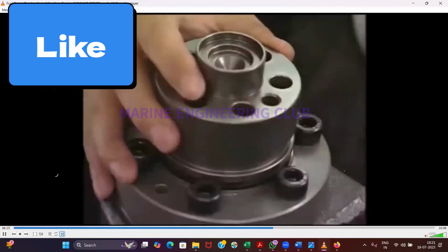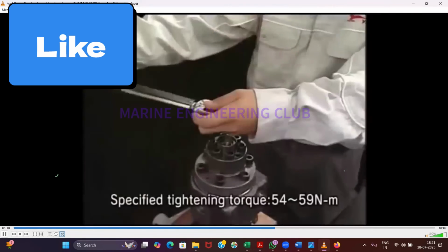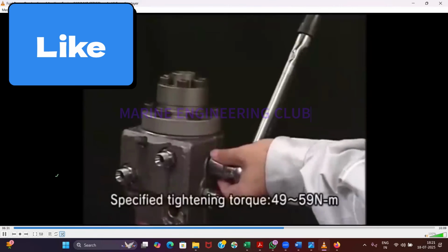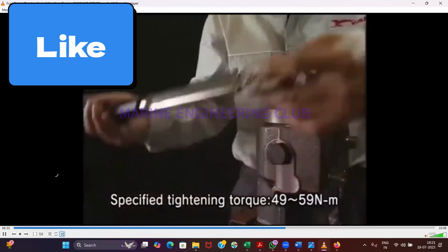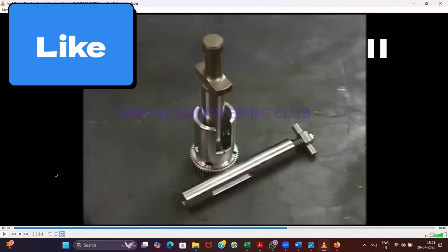You put your delivery valve again, top tightened, and then replace the deflector if you want, and tighten it with top tightening. Then you can put your control sleeve and your plunger that you are going to put now. This is how it looks, kept upside down, okay? Now here comes the zero setting. Here there will be 3 markings. One mark will be on your plunger foot, one marking on your control sleeve, and one marking on the rack. All these 3 should align together.